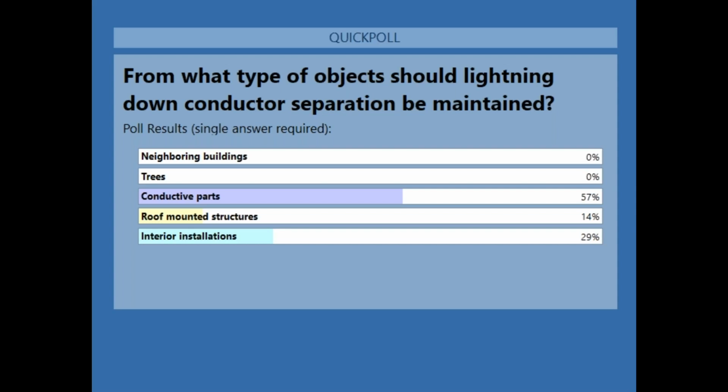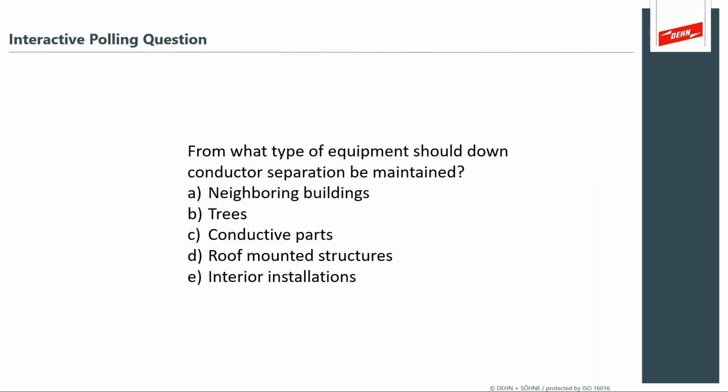And so when we're running our down conductor, it can be just inches away from what is in fact an emergency lighting, or a life-support oxygen line, or a hydrogen, maybe it's a gas line, and you're actually inviting a spark to black pipe or something where you don't want to spark over to. So these are really insightful answers about what we're looking for and what the audience is helping us with.